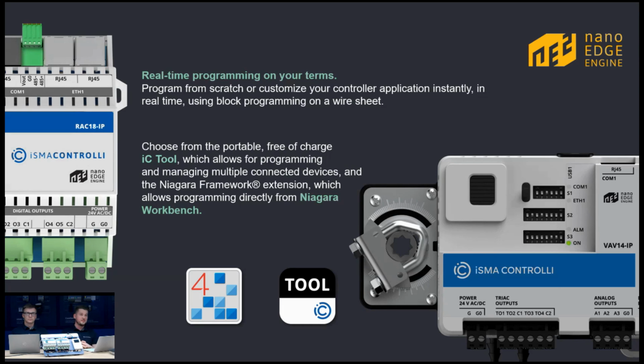For the users, we have prepared IC-Tool, which is our own free of charge and portable tool that allows real-time programming and managing of multiple connected devices. But at the same time, we created a special Niagara framework extension for our controllers that will allow not only to integrate the devices in Niagara framework, for that we'll use Modbus or BACnet, but will also give you the capability of configuration of the controller with the IP address, backups, application creation using the Niagara wiresheet, and of course, the whole commissioning process and integration. So this is what we have for you.